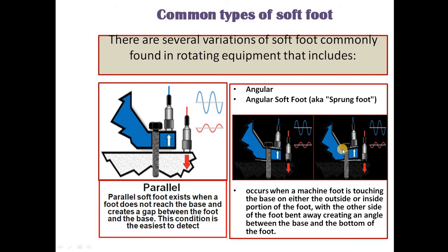To remove this soft footing, we cannot do it in position because a tapered shim is not available. So we have to take the base frame out, do machining here, make it parallel, and remove the soft footing.